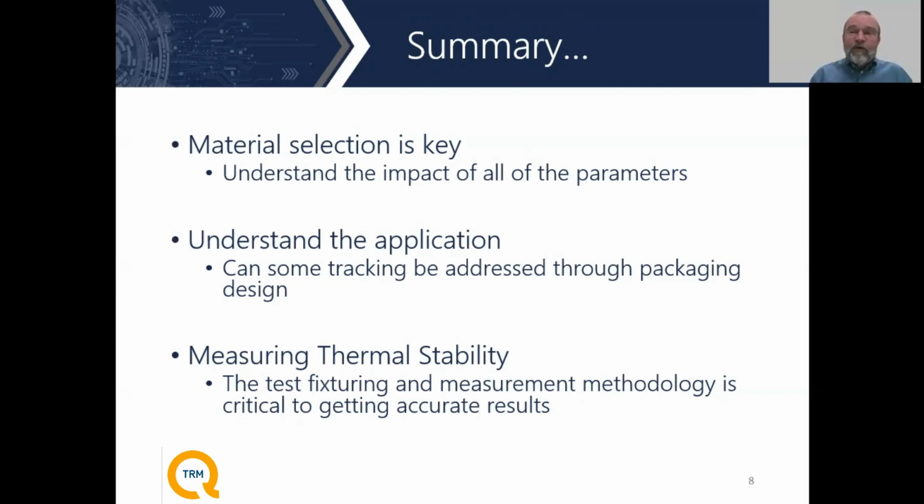Depending on the way that the cables run, they could mask some problems as well. So it's not always a worse situation by adding a cable in there. Sometimes they actually make it look better than what it really is. So the whole idea here is to make sure that what you're getting is accurate information by custom designing the measurement system to only measure the unit that you're looking for.